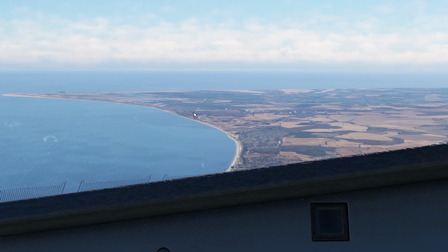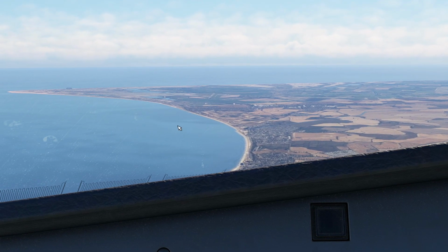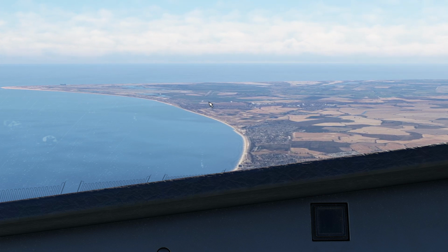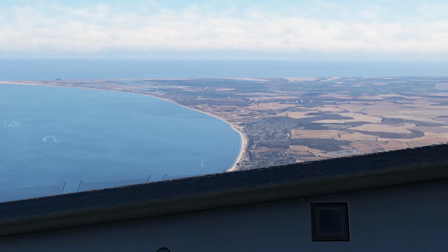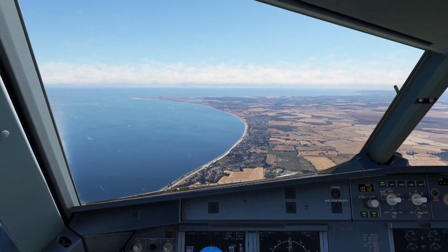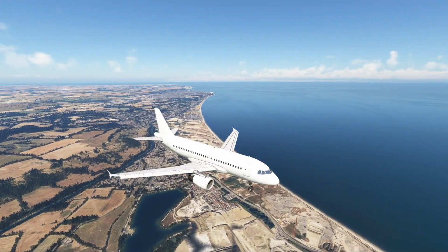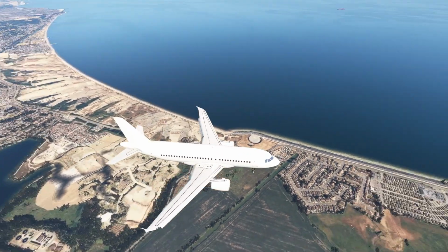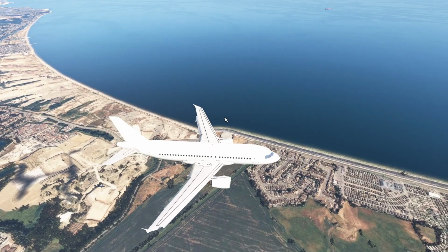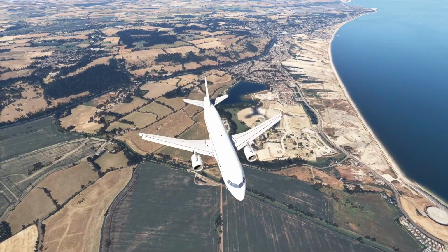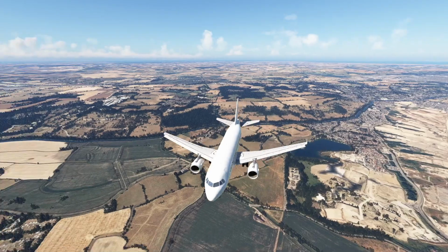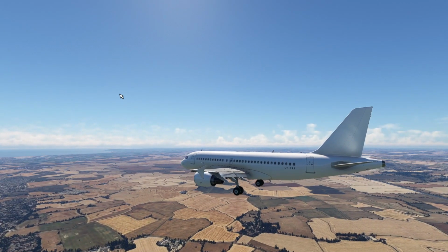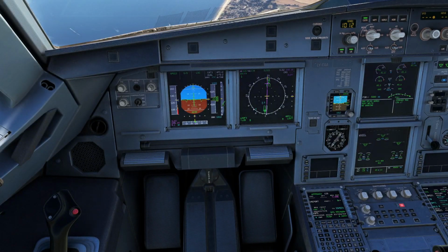You can see the extended runway track is a little bit different, about, as I briefed already, 5 degrees. 2500 checked, and it's a nice view of Ashford when going for an offset ILS approach down to the runway.